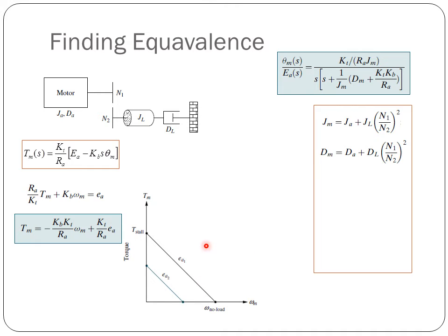So now this graph is going to help us in finding Kt by Ra and Kb. So how is that? I think all of us have done an experiment on this in your energy conversion lab. When we set omega equal to 0, that means we are here. According to this characteristic line, we will have a torque which is called stall torque.